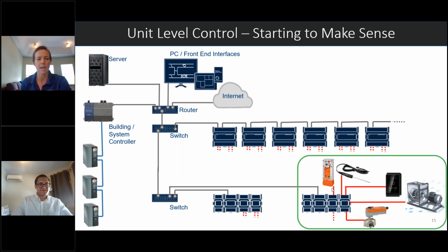Yeah, no, just to add on to what you said, again, these sessions are focused on HVAC controls. However, lighting controls, a lot of times what we'll do is integrate to lighting control. Typically these different lighting control systems might be essentially proprietary up until their gateway or master controller level, at which they become an open protocol like BACnet.